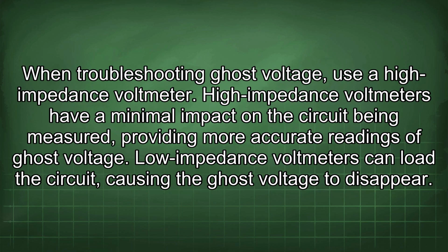When troubleshooting ghost voltage, use a high impedance voltmeter. High impedance voltmeters have a minimal impact on the circuit being measured, providing more accurate readings of ghost voltage. Low impedance voltmeters can load the circuit, causing the ghost voltage to disappear.